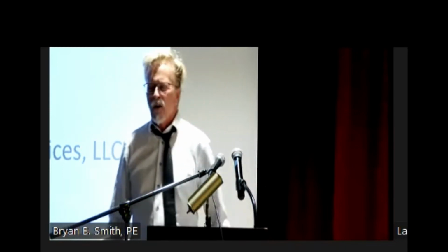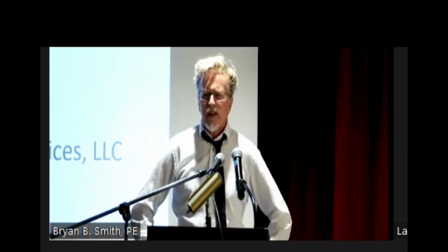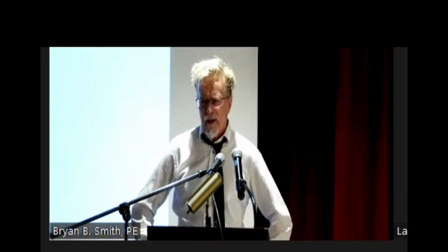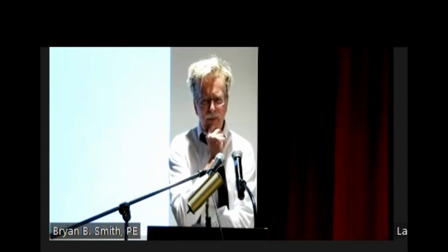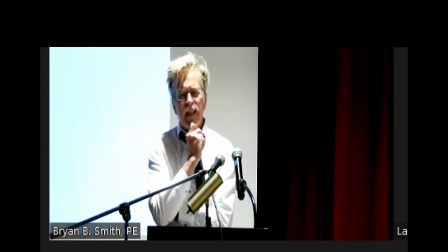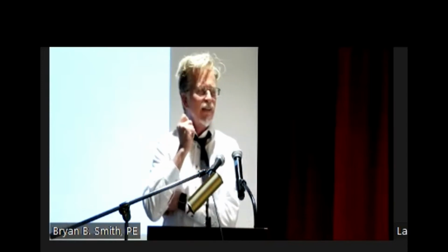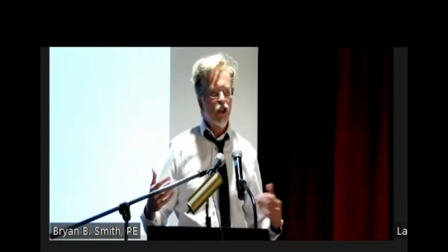All right. So from an engineering standpoint, we're like, I can take care of this. I need some thermal expansion. I need a surge vessel. I need my kids to close the valve slowly. Right. But what about that dishwasher or the washing machine? Or if we're in a high-rise hotel downtown, and every time they do a load of laundry, that 2-inch solenoid valve slams shut and the whole hotel goes. So this is surge and water hammer.